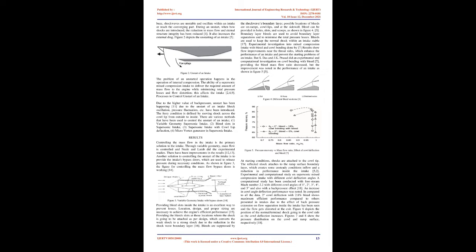At the time of operating conditions, shocks are generated as the intake is designed, as shown in Figure 1. Inside the intake, normal shocks are stronger than those normal shocks which are produced on transonic wings or in turbine machinery with upstream Mach.